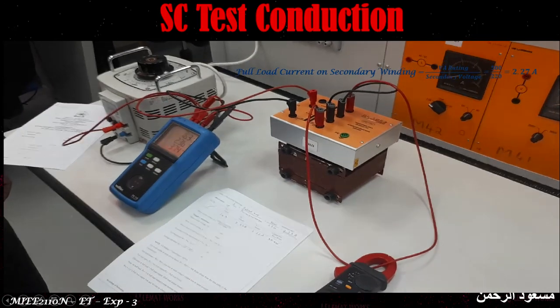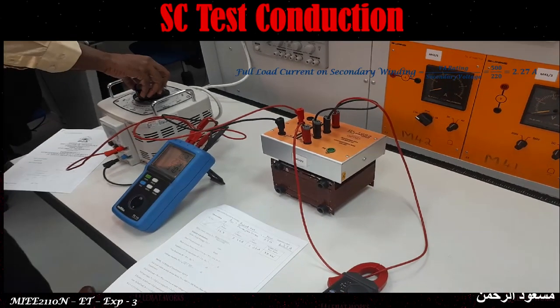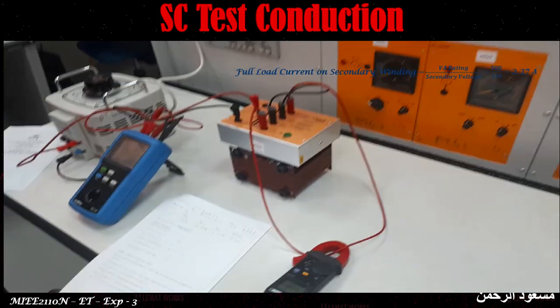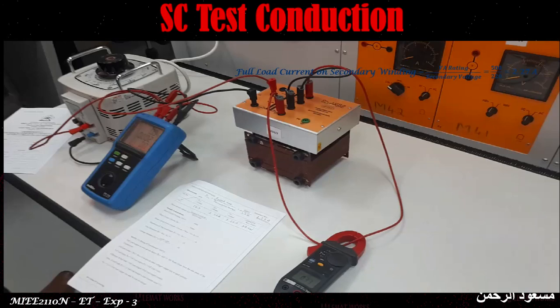After doing the test, we have to return the circuit to its initial position: reduce the auto transformer, switch off the auto transformer supply, and switch off the table supply. This is how we conduct the open circuit test and short circuit test. From the open circuit test we get the core loss, and from the short circuit test we get the full load copper loss. With these two losses, we can calculate the output power of the transformer from the VA rating and the secondary power factor. After reaching the output power, we add the losses to get the input. Output power divided by input power gives the efficiency.